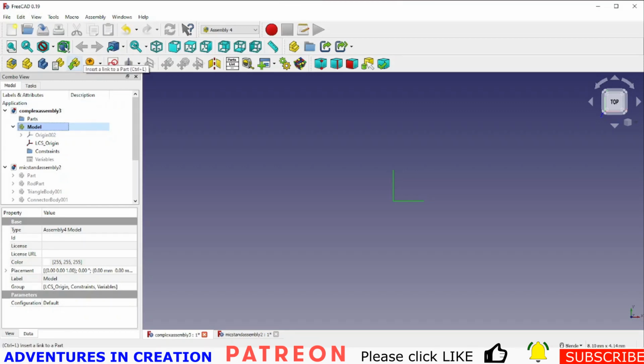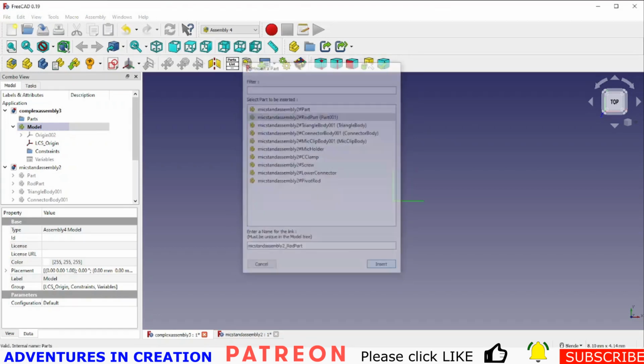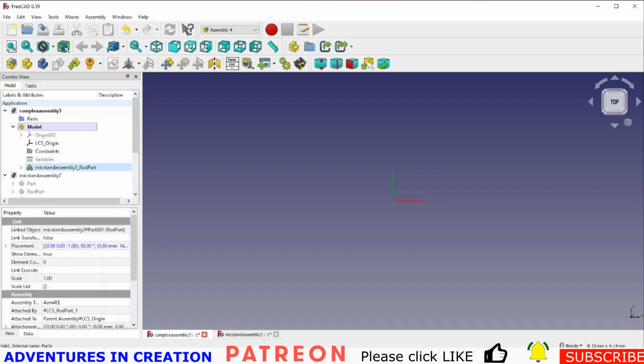Then I'm going to bring in a part. The first part I'm going to bring in is a rod body. Say insert. I'm going to bring it in by its first LCS, and I'm going to say it's going into the parent assembly by the LCS origin. And we'll just say OK to that.